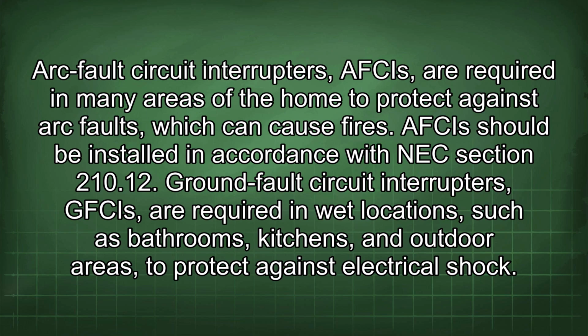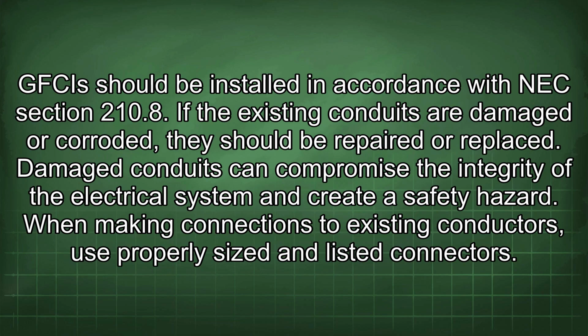Ground fault circuit interrupters, GFCIs, are required in wet locations such as bathrooms, kitchens, and outdoor areas to protect against electrical shock. GFCIs should be installed in accordance with NEC Section 210.8.